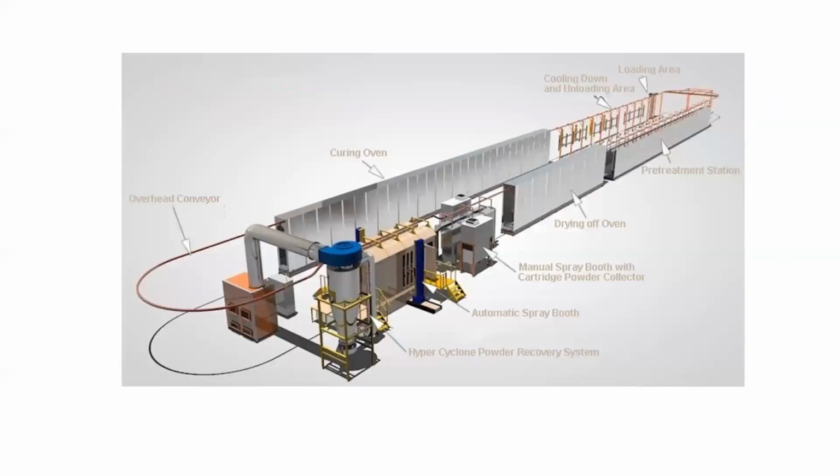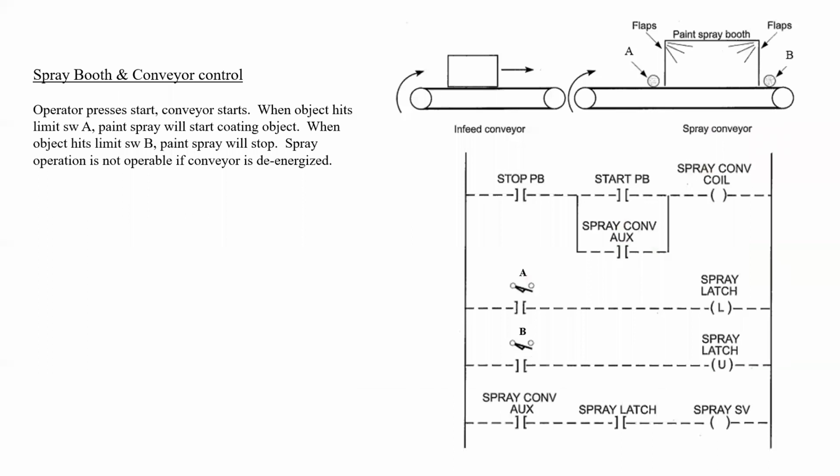This one is a little bit more involved, and it takes into account that we really want efficiency when it comes to spray booth operation. It would be best if the conveyor was somehow controlled by the PLC. That way, the spray booth won't turn on if the conveyor is not operating. This helps to reduce any sort of overspray and mess and wastage of product.